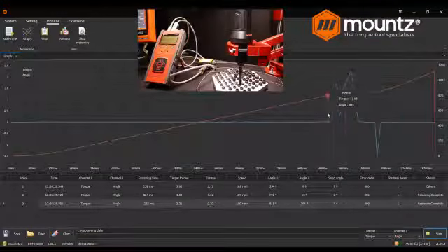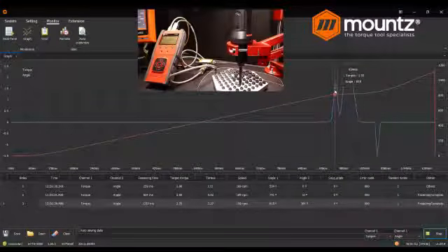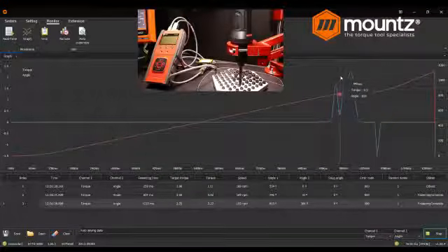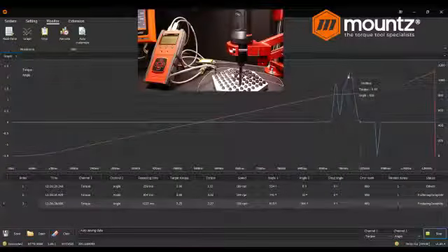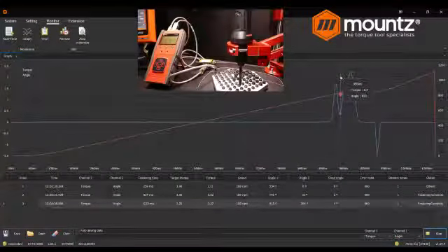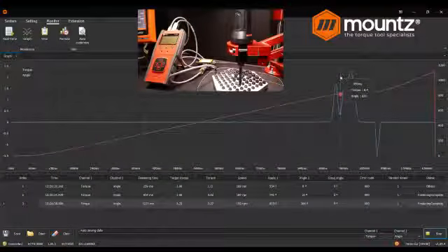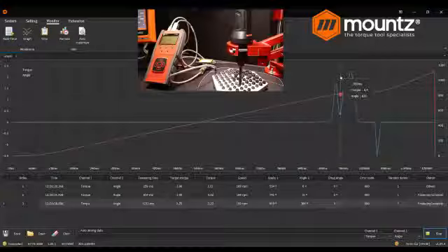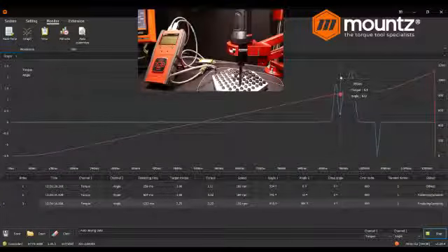So just before would be the end of the elastic portion of the fastener that would move into the plastic phase. And then you'd have your yield point at that point. So it would again look like the letter N, and the top of the N would be your yield point, or your failure point, depending on how far you took the fastener.